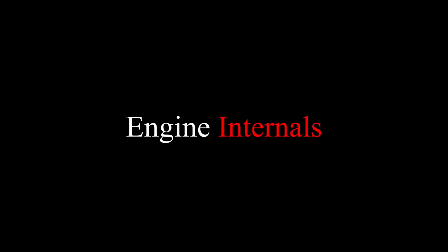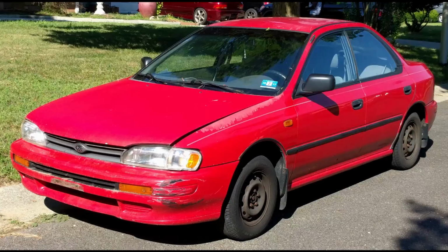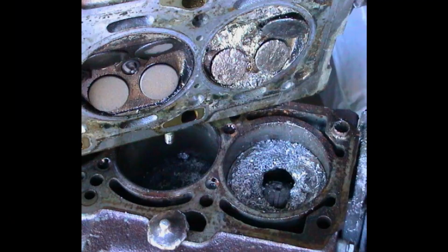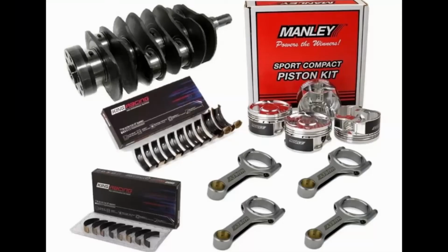If you have goals to significantly increase the power of your engine, you should consider how the internals of your engine align with that goal. If your platform was designed to be a low-cost eco-vehicle, like Benji, the engine internals will most likely not hold up well to a 35% increase in output. But on the flip side, if you start with a race-inspired sports car, it may be more resilient to and withstand those changes. In my opinion, once you hit around the 40% mark, you should definitely be considering upgrading your internals if reliability is important for your project.